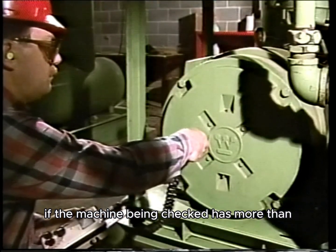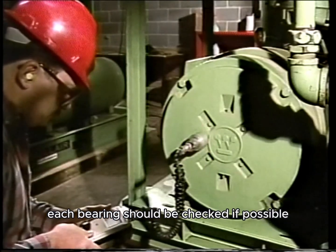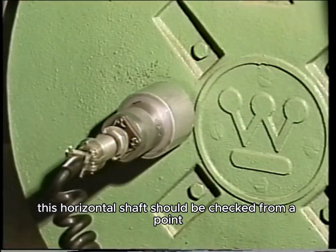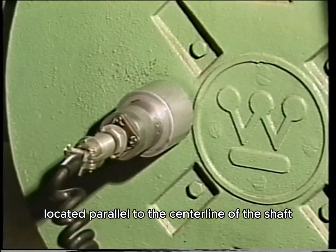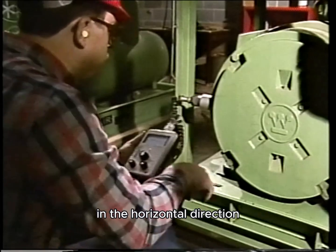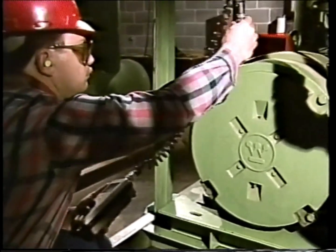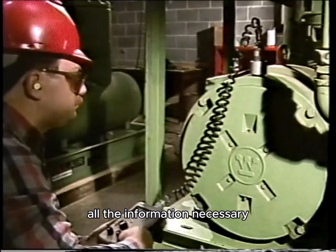If the machine being checked has more than one set of bearings, each bearing should be checked if possible. Also, each bearing should be checked from 3 different directions. For example, this horizontal shaft should be checked from a point located parallel to the center line of the shaft, then perpendicular to the center line in the horizontal direction, and finally perpendicular to the center line in the vertical direction. Checking from these 3 positions will provide all the information necessary.